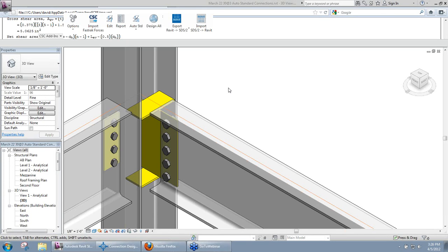You could go ahead and make the changes in both Revit and SDS2 yourself, or when you transfer the model to SDS2, all the setup information is actually transferred also. So as that gets transferred, when you import into SDS2, we go ahead and update all the setup settings to match them. So we shouldn't have to worry in that case when we're transferring models that our setup is going to be different.